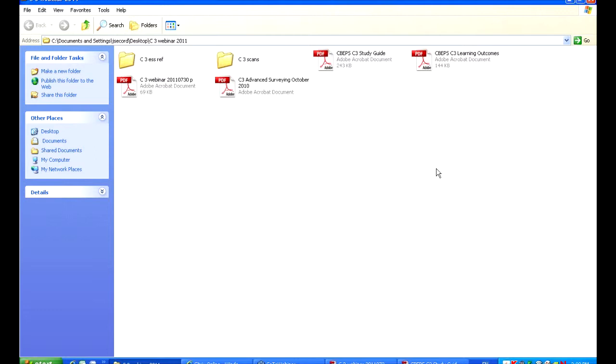Okay, 2004 October, and it was question 2, which was taking a three-dimensional traverse where you're measuring vertical circle readings and heights of instrument and heights of reflector, and having to reduce them mark to mark.